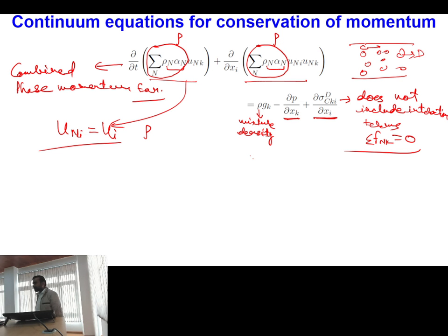So sir, there will be no relative motion between the phases either? There will be relative motion, but of course, if I am taking the assumption that the continuous phase is equal to the dispersed phase, then there is no relative motion. So shear will be zero in between, but not at the boundary. Yes. So that's why in the combined phase momentum equation this shear will come. But whenever I am writing the combined phase momentum equation, we are not at all bothered about that shear, because it is already equal to zero.